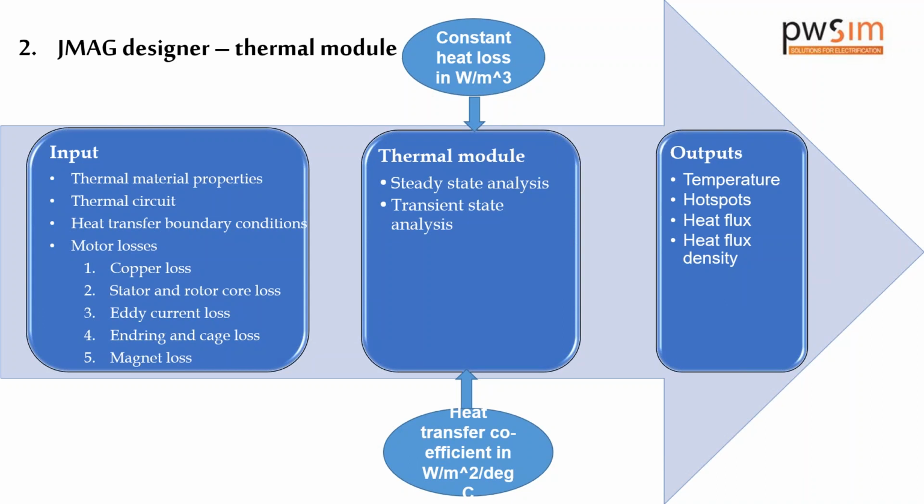Similarly, like you have seen in the 2D analysis, this 3D analysis of a motor using the thermal module will need you to give some inputs into the motor model. Now you have done the 2D analysis, right? So the next part you have to do is the 3D analysis. You have to do the 3D magnetic analysis before you go for the 3D thermal module. From the magnetic analysis, some of the inputs like the Joule loss, the heat loss, etc., you will be finding out using the magnetic analysis itself. That will come as an input to the thermal module.